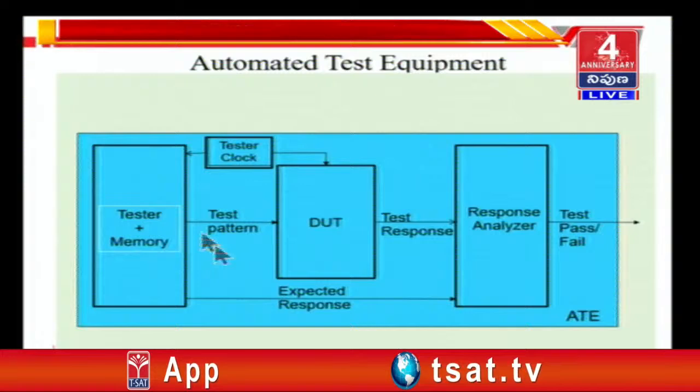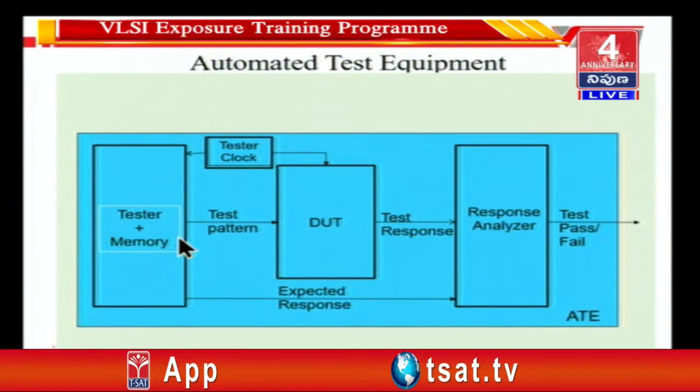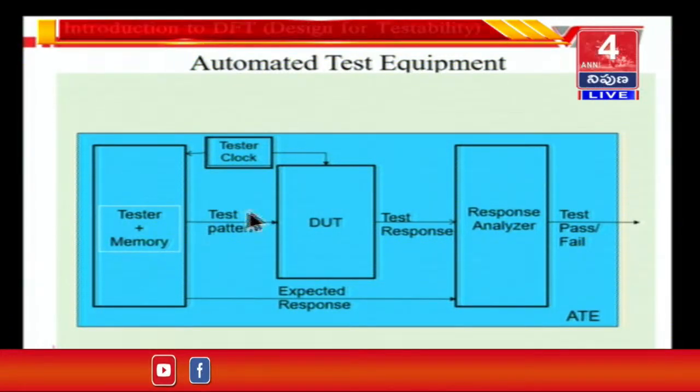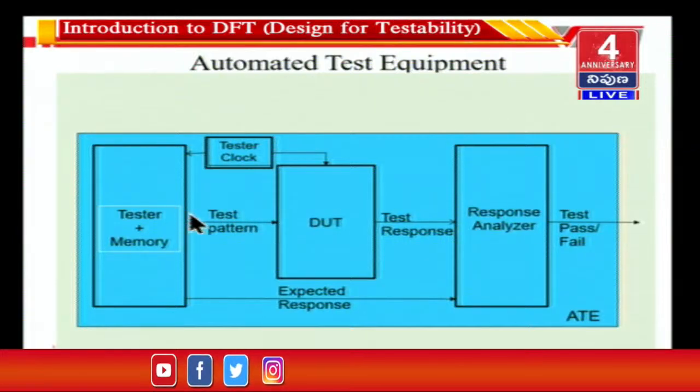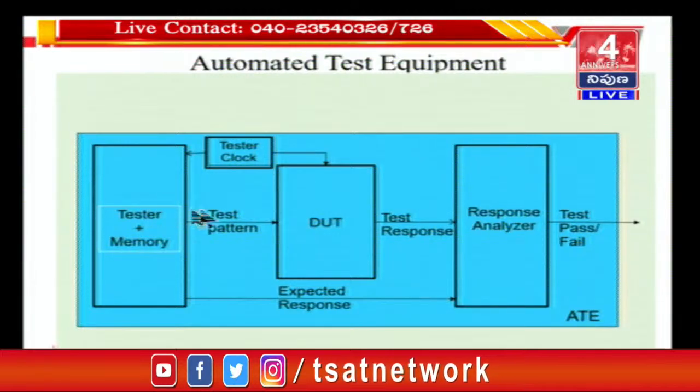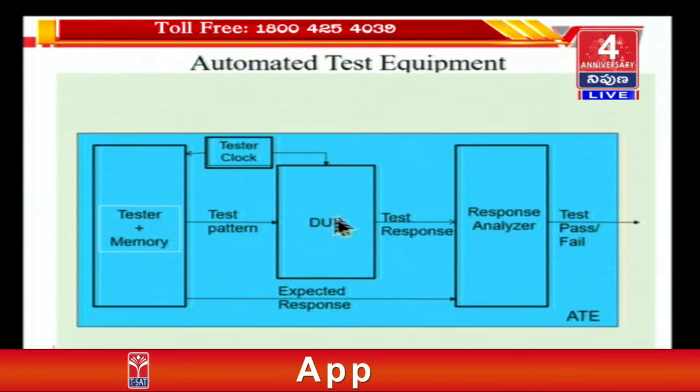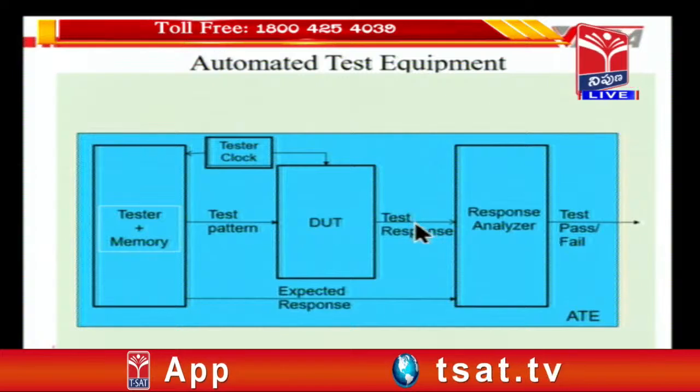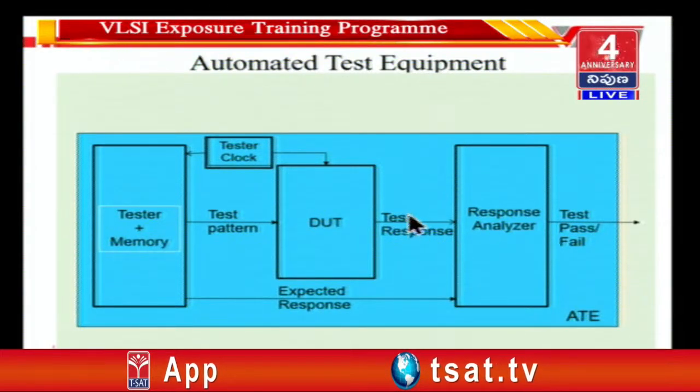So this is typically how the tester setup will look like, and we have a tester clock, we have a tester pattern. This is the pattern that has been loaded into the tester and it is applied to the DUT. The DUT will give the response at 90% of the cycle time. At 9 nanoseconds the response comes.